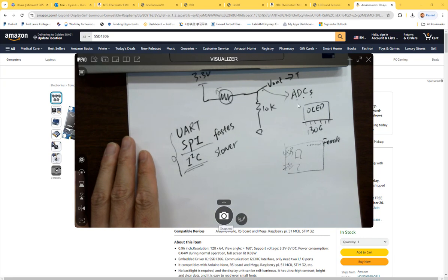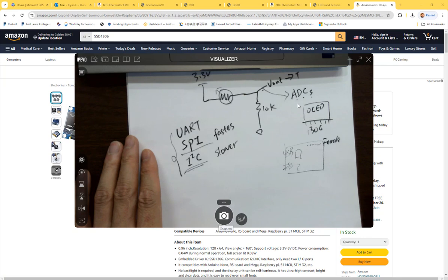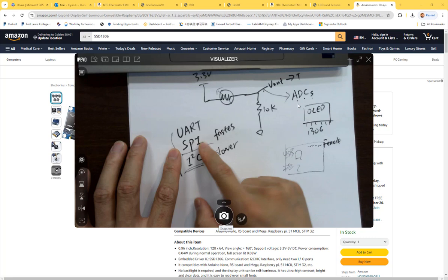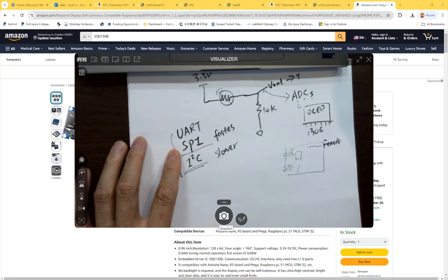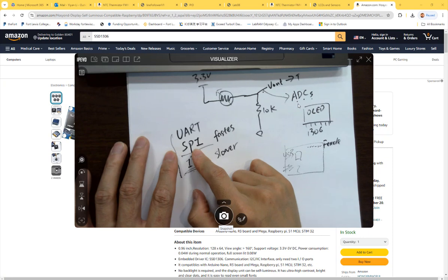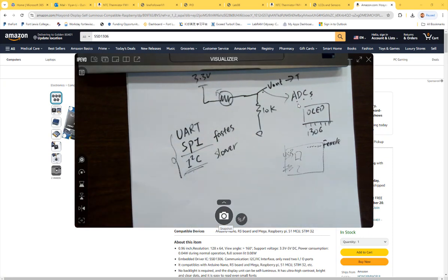So, like, for wires, you want a faster connection because it's hardwired. But if you have something like radio waves or something even slower, then you want a slower transmission rate. Mm-hmm. It depends on the applications, right? So for the SD card, it's a pretty short connection on the board, and we usually use SPI for SD card communication. So we are getting into the SD card application in Lab 9.